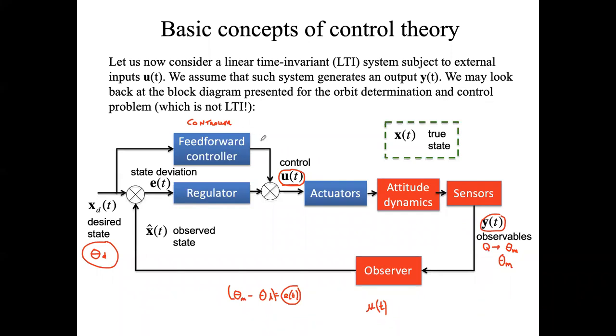It is important because it is what we need to apply to, for example, the reaction wheel in order to keep a certain attitude. So the controller is going to provide our Tc, the control torque, that we need to apply from the actuator. The actuator is going to apply this Tc, and the dynamical equation, the Euler equations, will account for the control torque that we received from the controller to change our state. And so the loop is going to be closed with additional measurements from our sensors. They go back and give us the estimated measurement state, and the loop will continue until we reach our desired state.